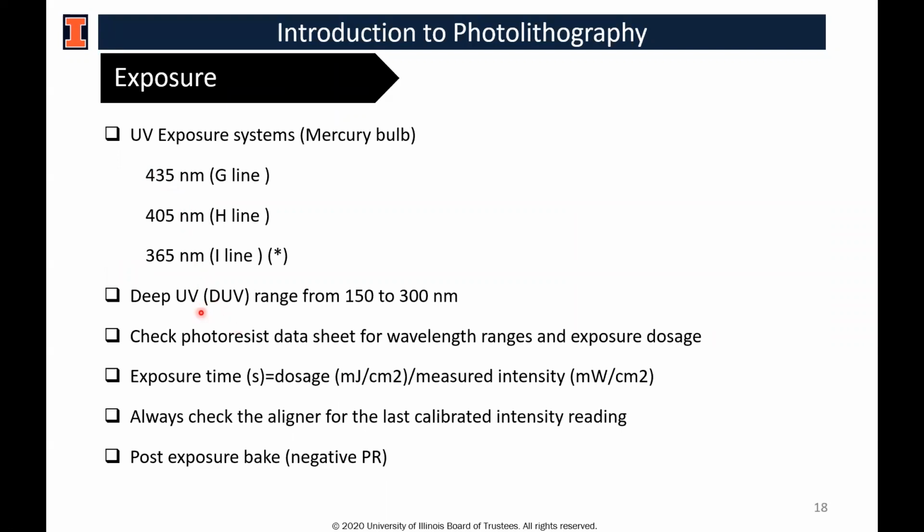It's always important to check the photoresist data sheet for the wavelength ranges and exposures of the dosage that you're going to use. And we also recommend that we always check the aligner for the last calibrated intensity reading. Now, if you're using a negative photoresist, a post-exposure bake is necessary.